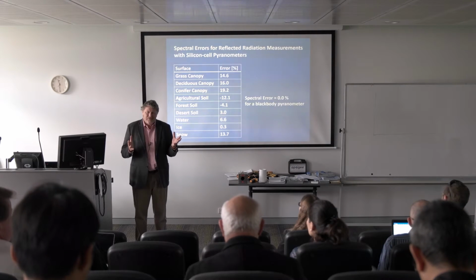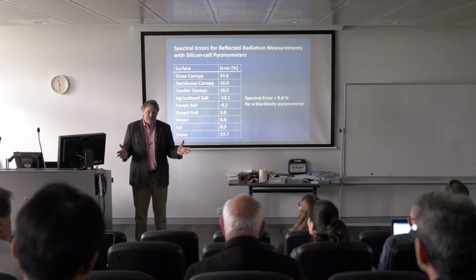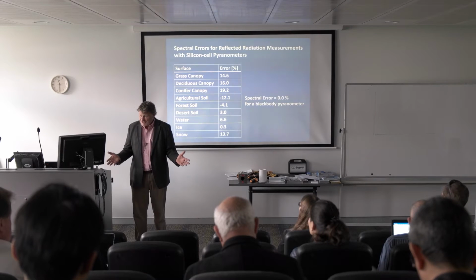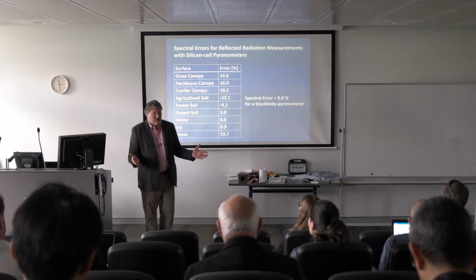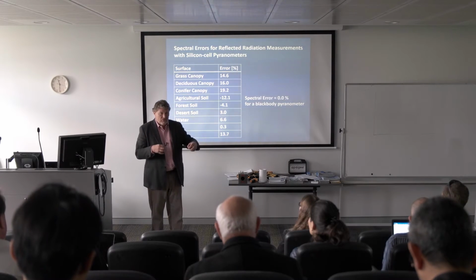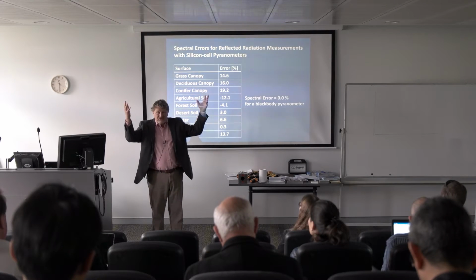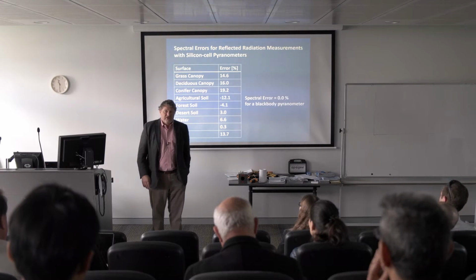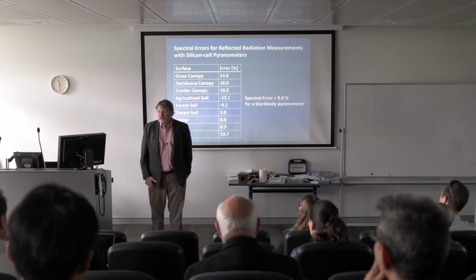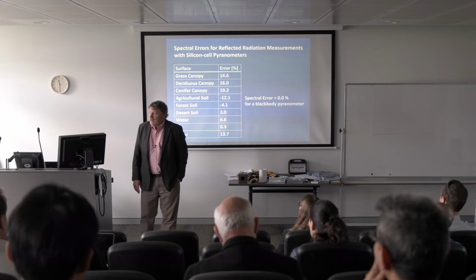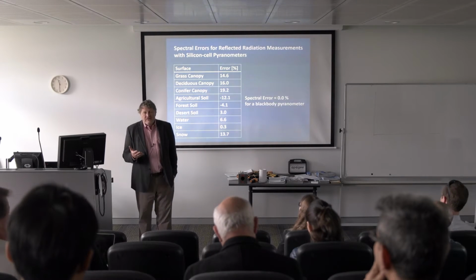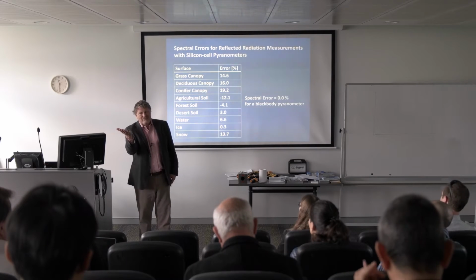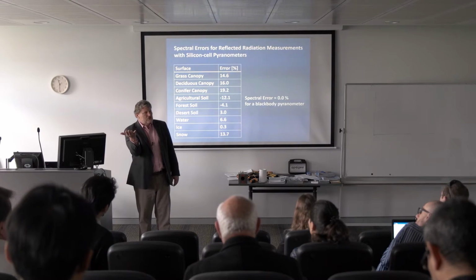Part of what we want to help you do is evaluate specifications of instruments. You don't need to overbuy expensive instruments, but if you understand the specs, sometimes you can get away with less. Often you can get away with less than the highest cost instruments if you really know what you're doing and the limitations of the sensors. Leveling is a big source of error. The sensors drift. They become unlevel. Boy, people don't check that often enough.